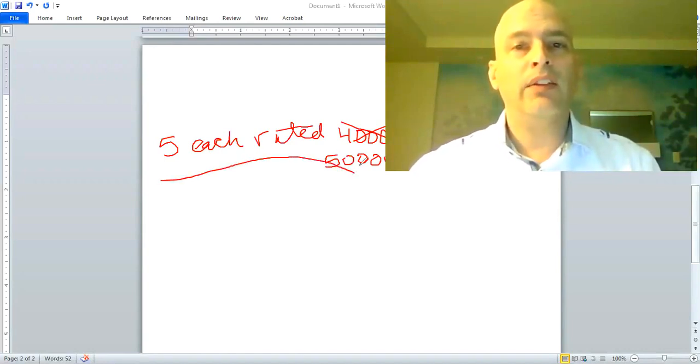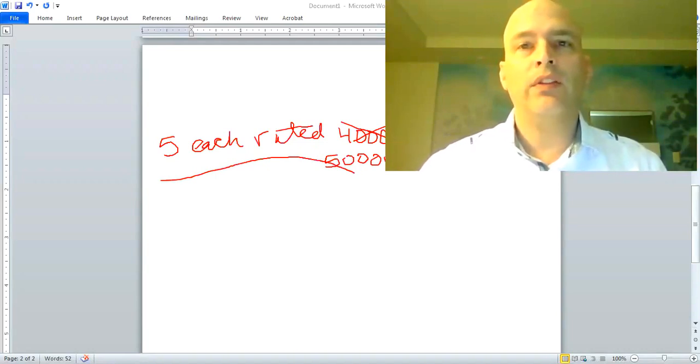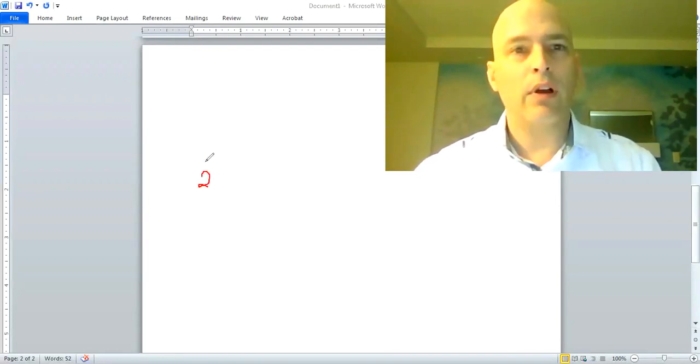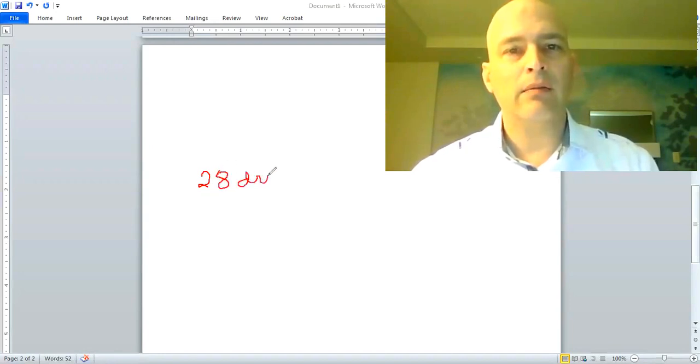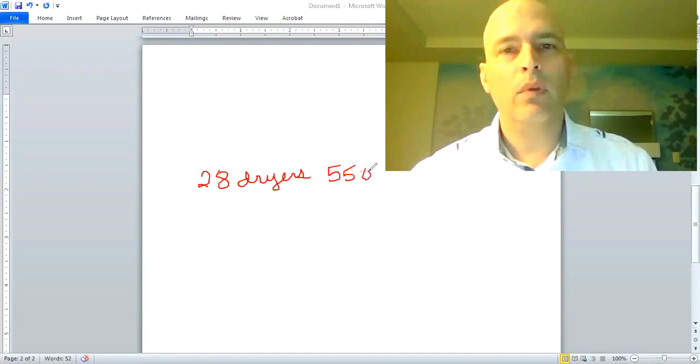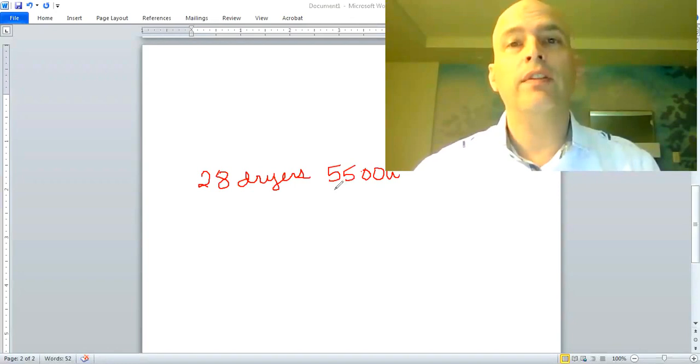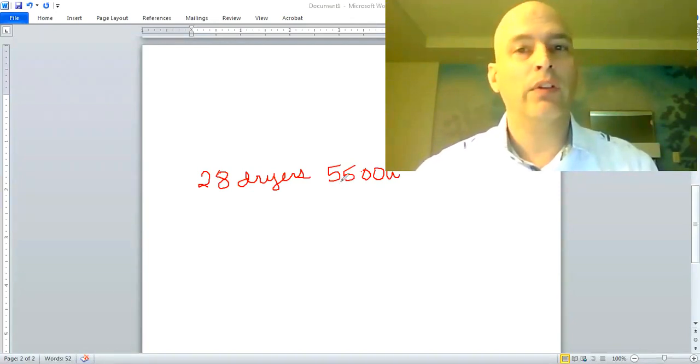All right, let's say that we had a set of dryers, we'll just say we had 28 dryers. And just to make it easy, let's just say that each nameplate was rated for 5,500 watts. Now, what happens here is that because I use 5,000 as a minimum number or the nameplate, whichever's larger, I'm going to be using this 5,500 watts, not 5,000 watts in this case, okay?